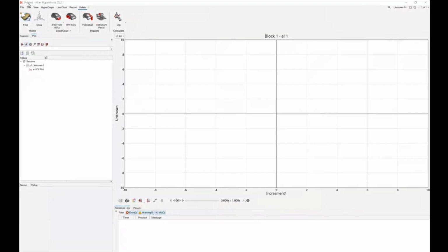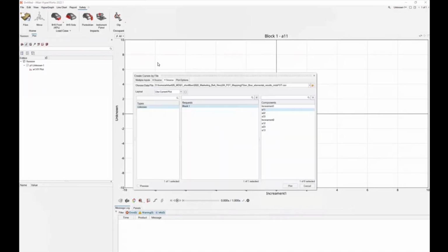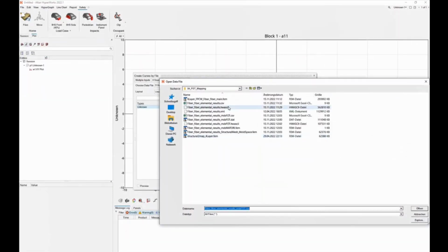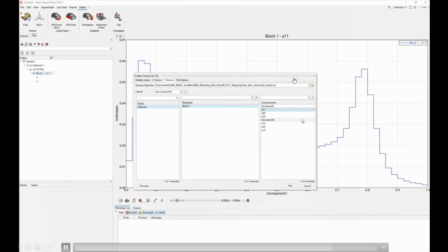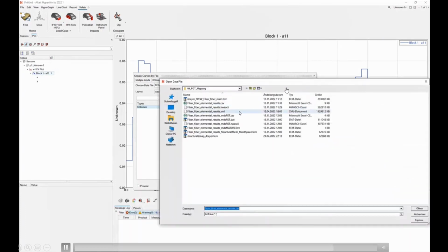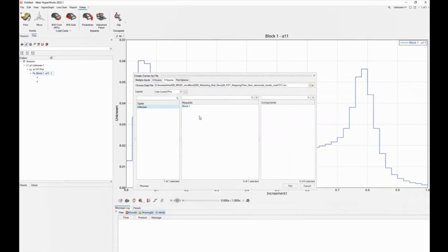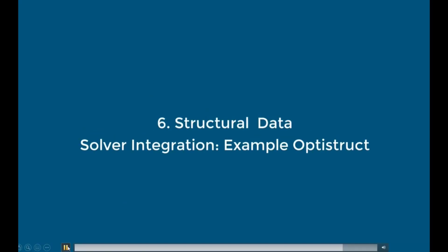And then we can also, for simplicity, check how well the things were basically mapped. One of the files that's created in the process is a curve that you can compare between the original and the mapped one. So now if we for both of those look at the A11 in the fiber orientation tensor, you can basically see how that affects.